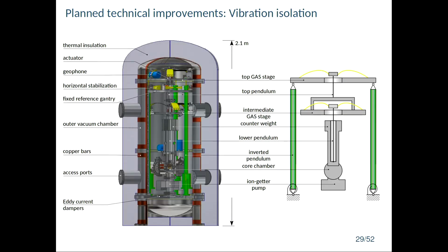So also on the vibration isolation, we improved a lot. This is designed with a two-stage system. We're using here non-linear mechanical elements. These are inverted pendula and geometric anti-springs. This is technology that has been developed actually for gravitational wave detectors, and we are using it quite successfully.